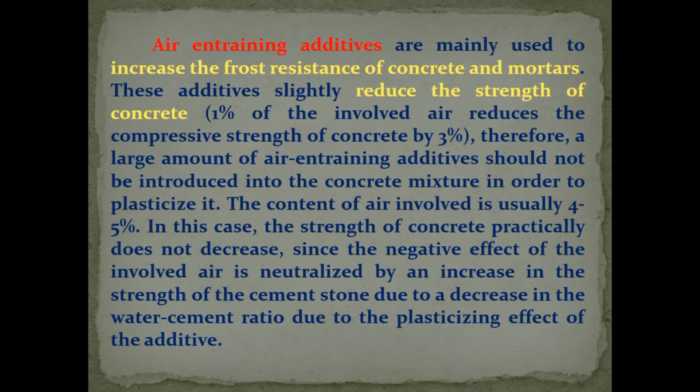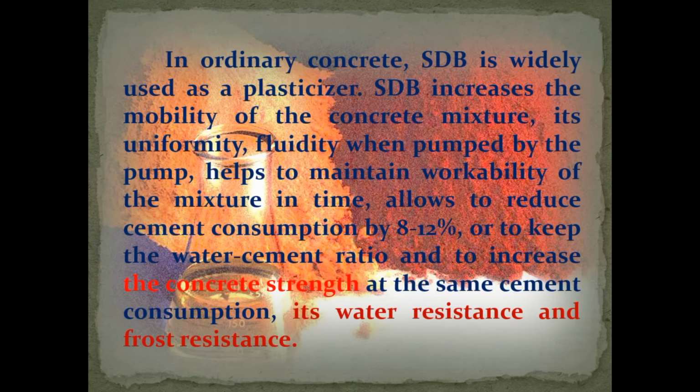Air entraining additives are mainly used to increase the frost resistance of concrete and mortars. Their use slightly reduces the strength of concrete: 1% of entrained air reduces the compressive strength of concrete by 3%. Therefore, a large amount of air entraining additives should not be introduced into the mixture.